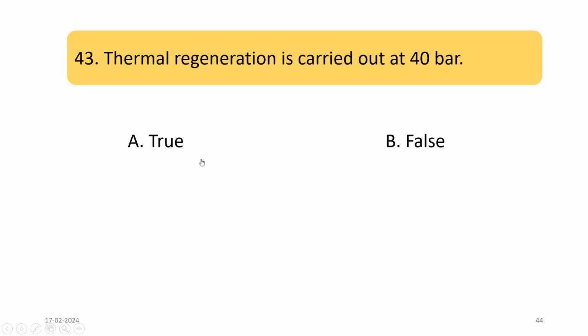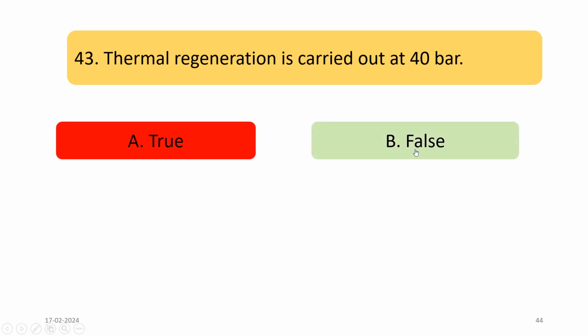So thermal regeneration is not carried out at 40 bar, because 40 bar means high pressure. Thermal regeneration is carried out at low pressure, that is around 1 bar. In high pressure, adsorption is carried out.